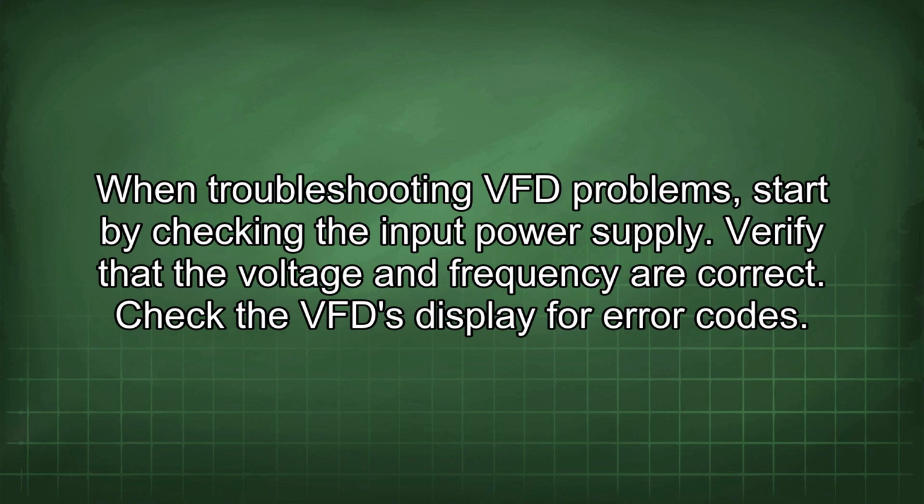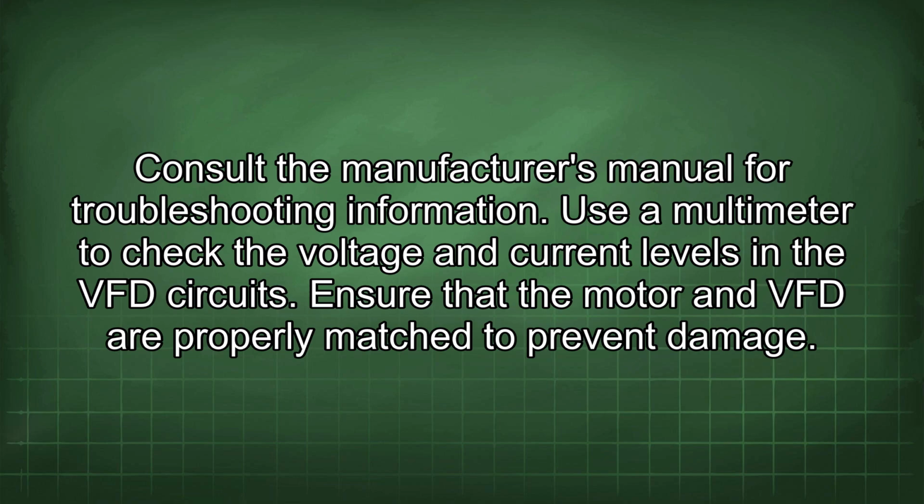When troubleshooting VFD problems, start by checking the input power supply. Verify that the voltage and frequency are correct. Check the VFD display for error codes. Consult the manufacturer's manual for troubleshooting information. Use a multimeter to check the voltage and current levels in the VFD circuits.